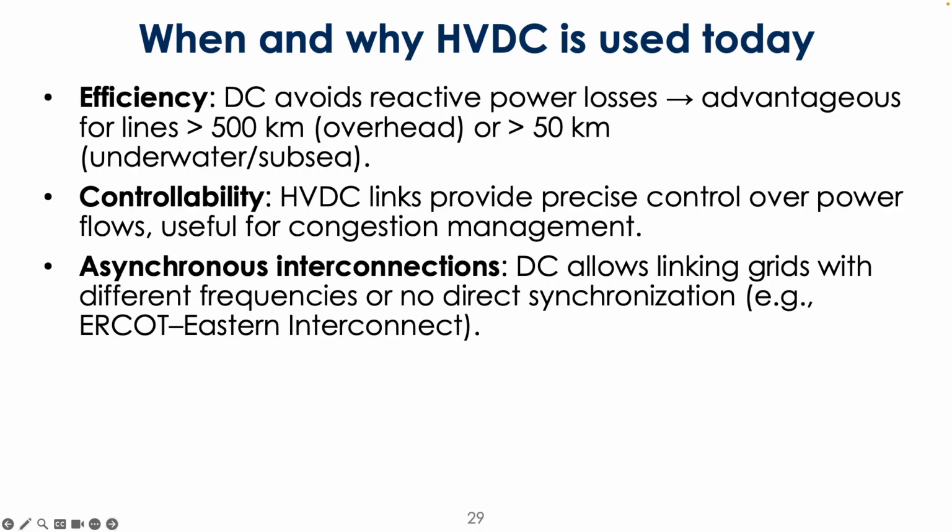There's almost like an electrical momentum to keep you in line with what everyone else is doing. And so if you are slightly below the frequency, and I'm saying very slightly, right, and you're connected on, you will feel pressure to speed up a little bit.